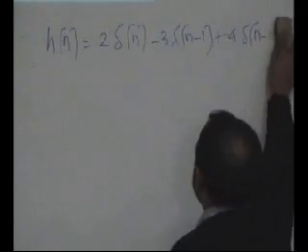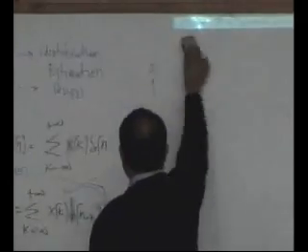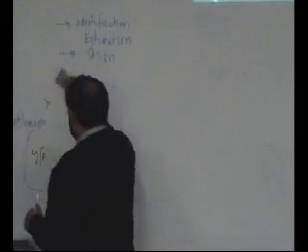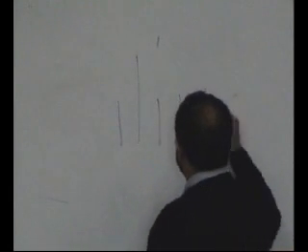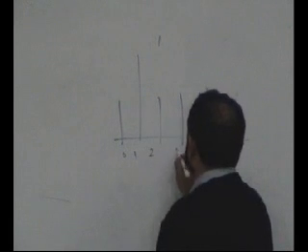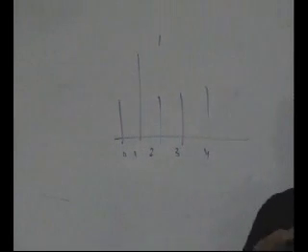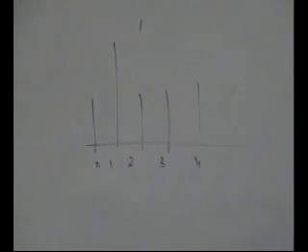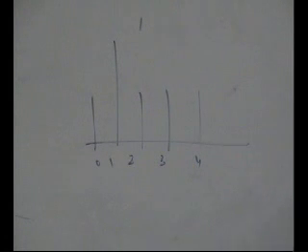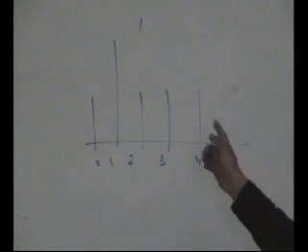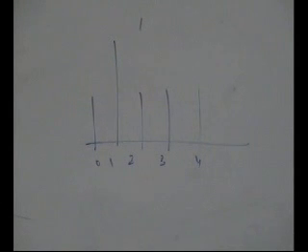I'll give you an example which you can figure out by yourself. I have a signal and I want to take out the DC value from it. I want to take DC away. DC is the level, the signal is riding on some constant value, and I want to take that away. I want you to design a system. A system is very simple to design. You add the current value in the previous value. Right? This will be a good system.